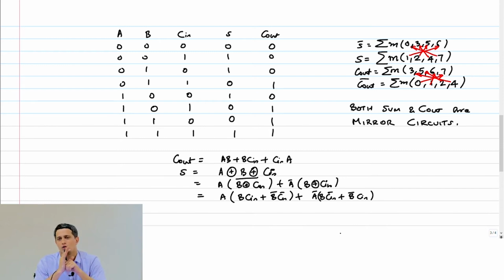Yeah, it's basically going to be a very complex circuit. Okay. And therefore it's not, and also you need to have A and A bar now. Only then I can even implement that static CMOS logic correctly. Right. So therefore it's not even wise to go this way. You need A bar, B bar and so on, C bar, and also stack is huge.